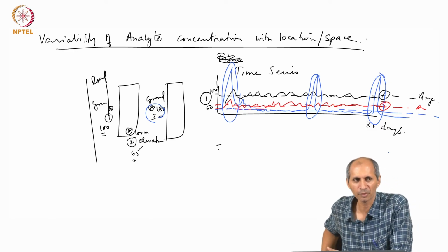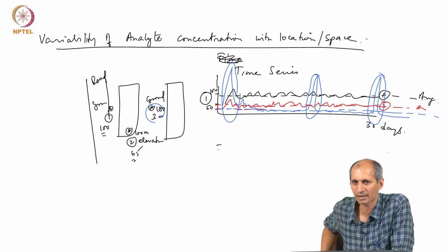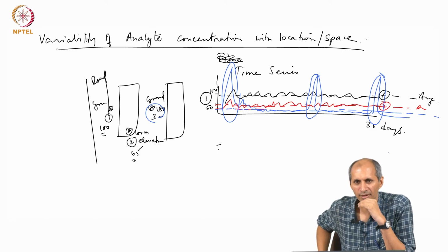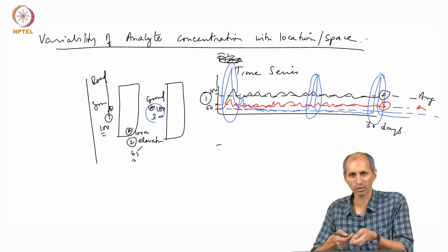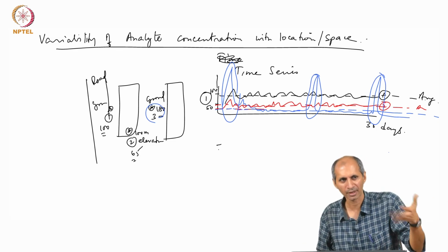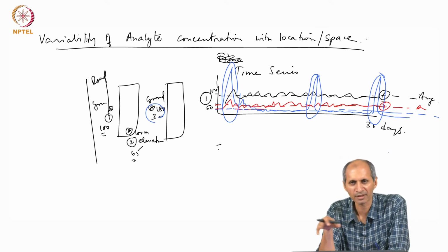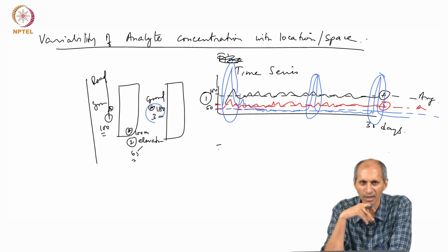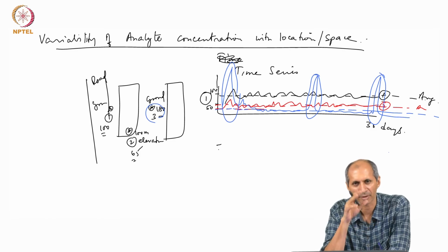So, there is a spike, a very special activity that is happening say once a week. It could be things like people sweeping that entire area and cleaning it. Sometimes people clean roads by taking a blower and blowing. In this campus they sweep. When they sweep, there is a lot of dust locally for a short period of time. If you are sampling in that time, you will see a spike, but it does not happen anymore. Between these two buildings people sweep on soil, which generates a lot of dust. It does not mean there are any other sources, it is not a recurring source, it happens once a week or once in 2 weeks or so.